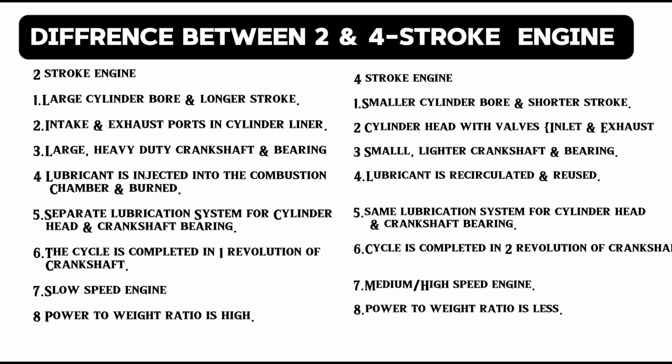In 2-stroke engine, lubrication oil is injected into the combustion chamber and burned. In 4-stroke engine, lubrication oil is recirculated and reused. In 2-stroke engine, separate lubrication system for cylinder head and crankshaft bearing. In 4-stroke engine, same lubrication system for cylinder head and crankshaft bearing. In 2-stroke engine, cycle is complete in 1 revolution of crankshaft. In 4-stroke engine, cycle is complete in 2 revolutions of crankshaft.